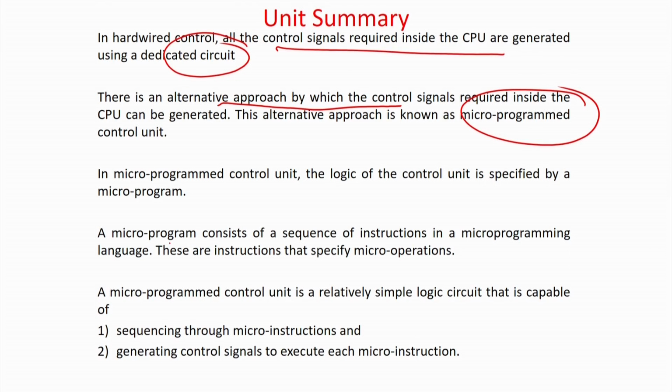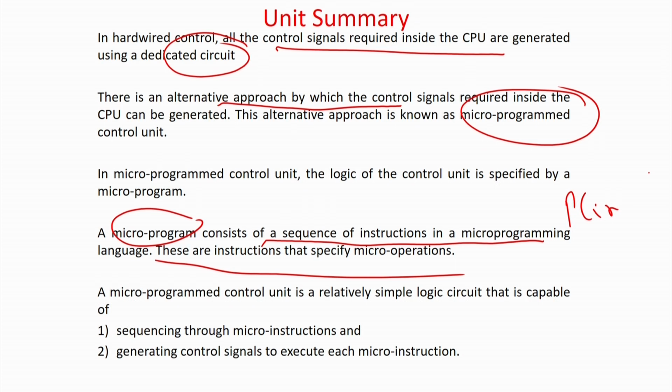A microprogram consists of a sequence of instructions. A microprogram corresponds to a sequence of micro operations; that is very well known, that a macro instruction has some micro instructions, which we have already discussed a few lectures back. Corresponding to each of the micro instructions or micro operations, we have some control signals, for example PC in should be equal to 1, etc. Those bits we can make 1, and whichever are not required we make 0 and store in one word of a microprogram control memory.